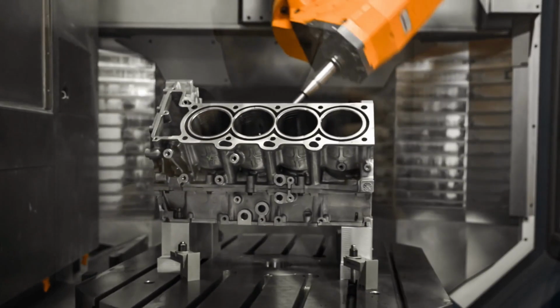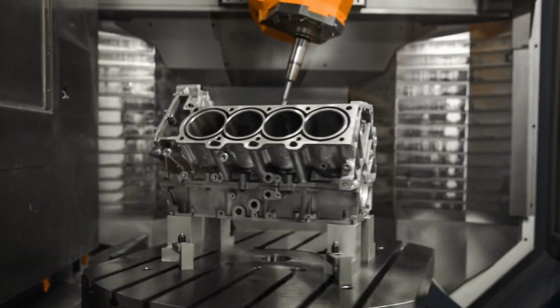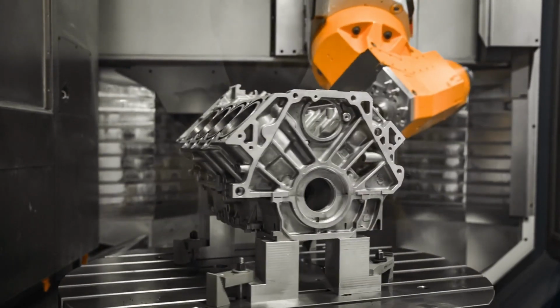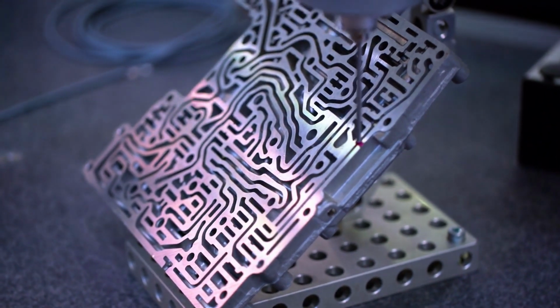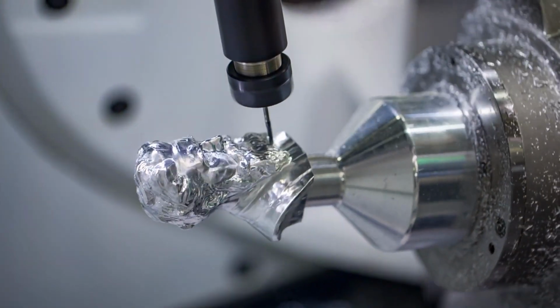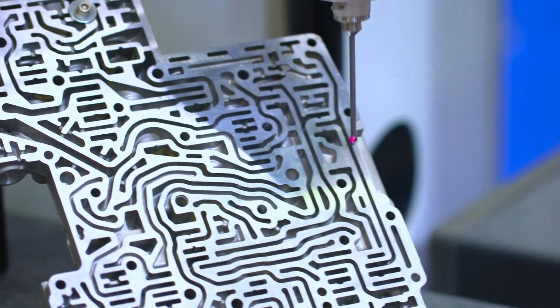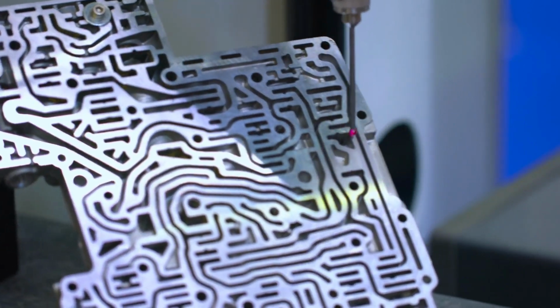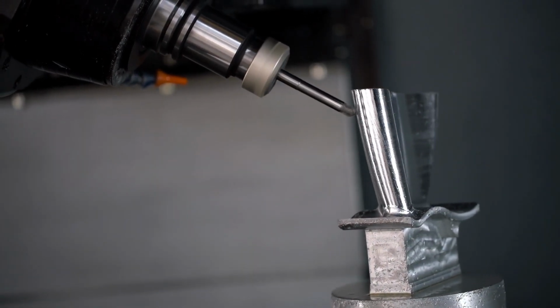Understanding the difference between the movement of your tool and table is easier to show than explain with words. Your CNC machine's origin. Every CNC machine has its own internal origin point called machine home. When your CNC first boots up, it has no idea where it is in physical space and requires a calibration to get its bearings. When this process occurs, all 3 axes of your CNC move towards their maximum mechanical limit. Once a limit is reached, a signal is sent to a controller which records the home position for that particular axis. When this occurs for all three axes, the machine is now homed.